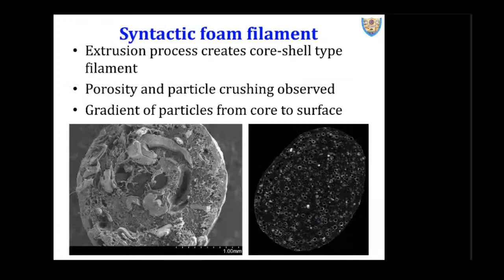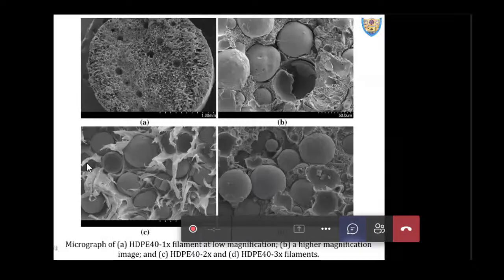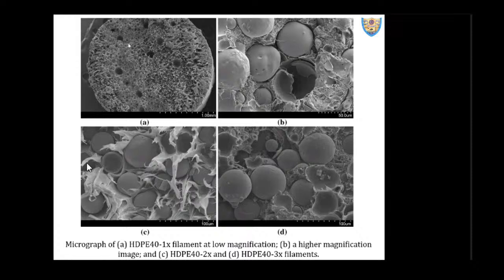Additionally, because there are entrapped air pockets here, let us say by infusing 60% cenospheres in this filament, I'm reducing the weight by, let us say, 30%. That is the maximum, right? Above 60%, particles will fail, and if the particles fail, density will sharply shoot up. Rather than the filament floating, it will start sinking if the particles break. So what happens if I have additional air pockets? I can go even above 30%. With 60% microballoons, I can reach a maximum of 30% weight saving.